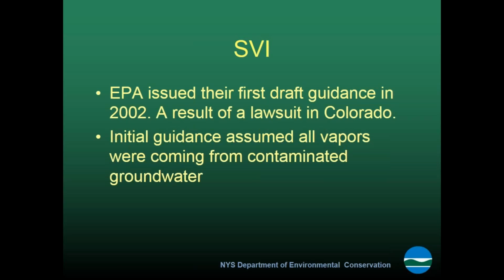If you have a release of contaminants from a building, from a dry well inside a building, for instance, the area underneath the building isn't flushed by rainwater, so you tend to have a higher concentration of the organic solvents in the vadose zone above the groundwater, and those will act as a continuing source for the solvents getting into the building, and it's definitely something to be aware of for vapor intrusion sites.